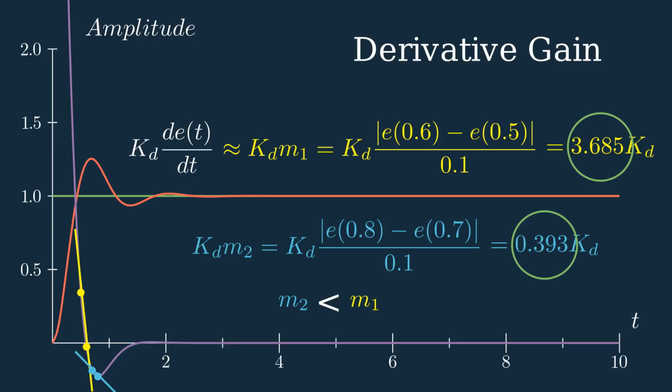So to summarize, based on the current rate of change, we're able to determine the speed of the response, and the derivative component will compensate for higher speeds by having more of an effect on the PID output, since there will be a larger rate of change.